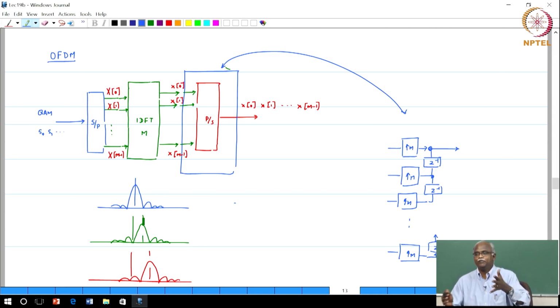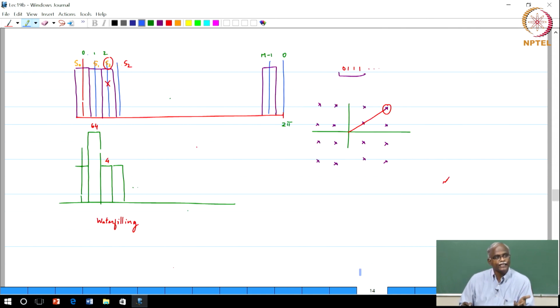So when you apply them, you automatically get the translation from time division multiplexing to frequency division multiplexing. Of course, this also gives you a lot more insight into when you do not transmit on a particular channel or carrier, and when you boost the power of a particular carrier. Again, all of these are flexibilities that come into play when you have an OFDM system.